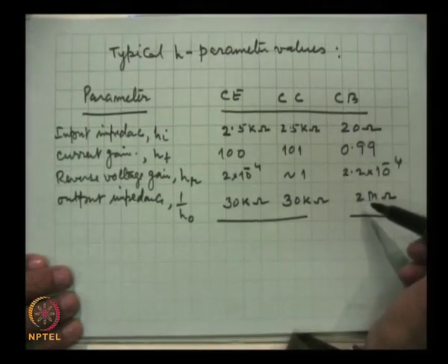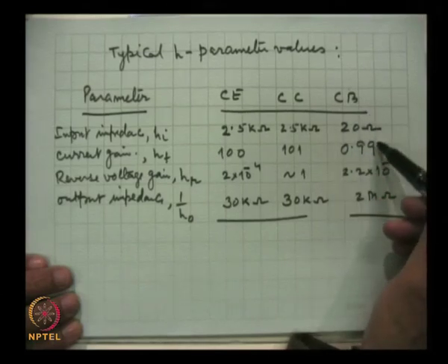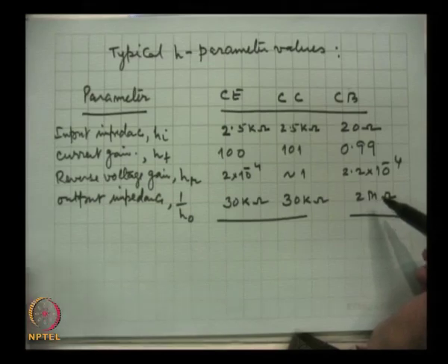That means 2 common base circuits cannot be connected together because of the large difference in the input and output impedance. You must have done the power transfer theorem, which indicates that from one circuit to the next circuit, power transfer is most efficient when the impedances are matched.